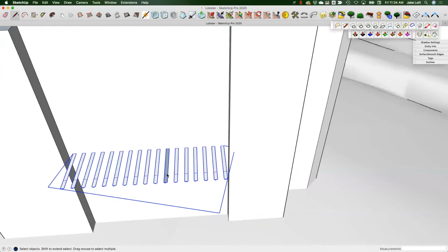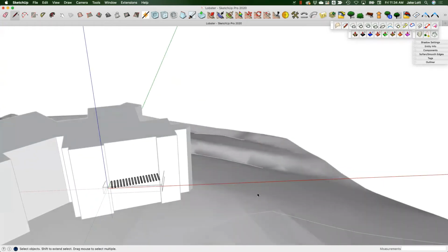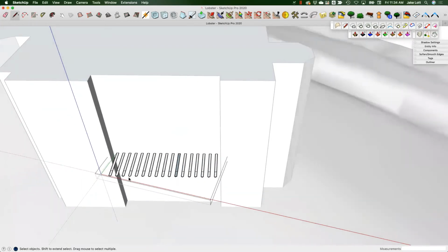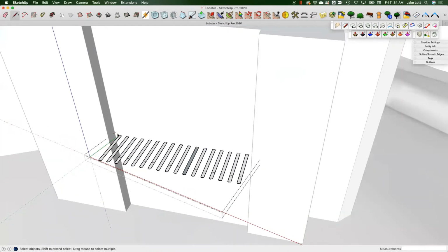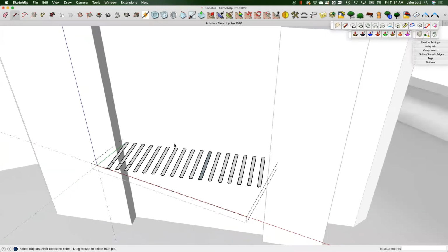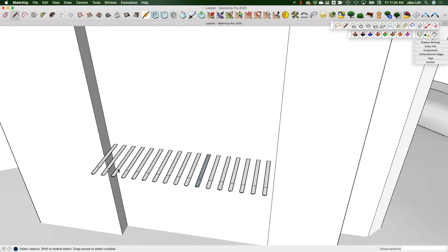You might be used to it, and if you double click inside, you can see that it's showing you that temporary axis point of where it created that group. Well, that's not what we want in order to quickly draft stuff, okay? We want to be able to make sure that our inference points, and as we're inferencing things, that this direction is our red and our green, because that's going to make a lot of things much simpler to draft, and I'll explain that to you by giving you this little demonstration.